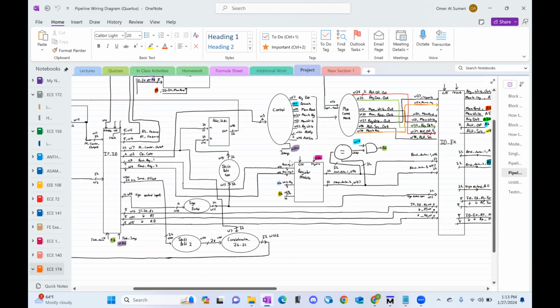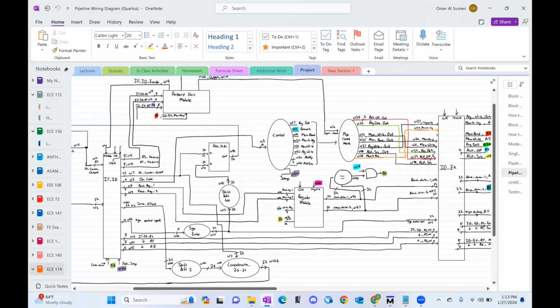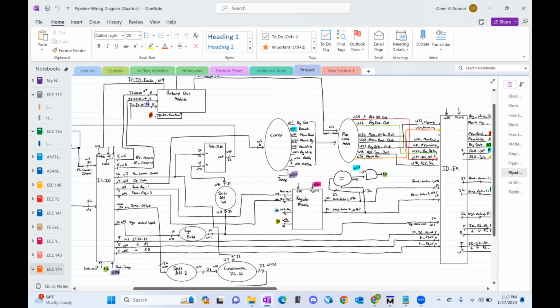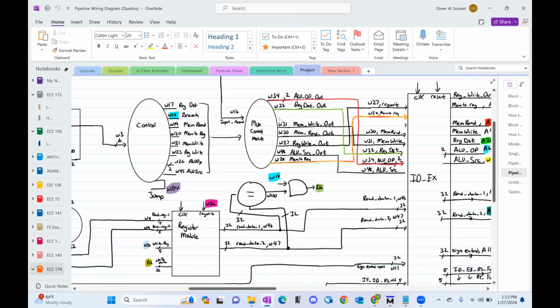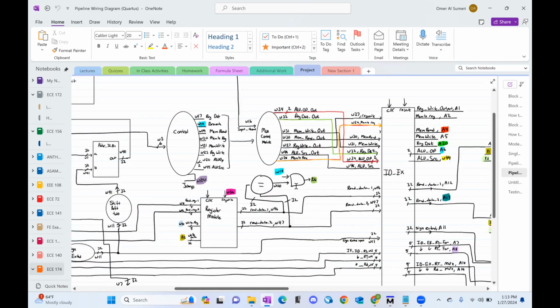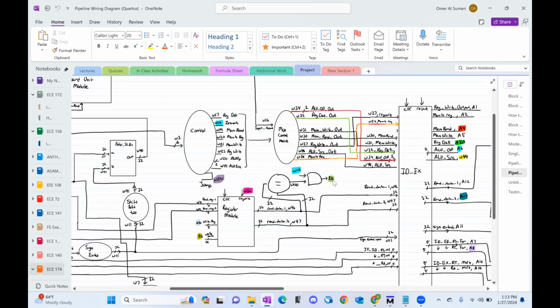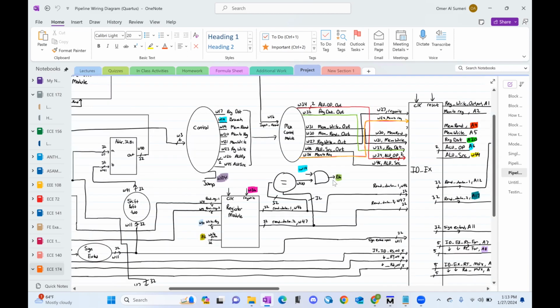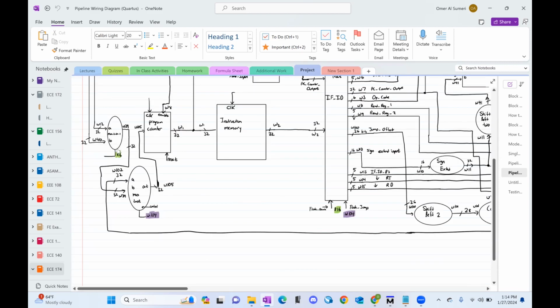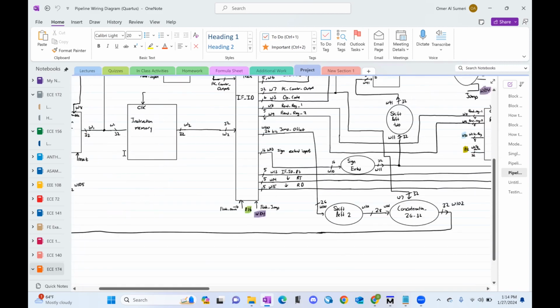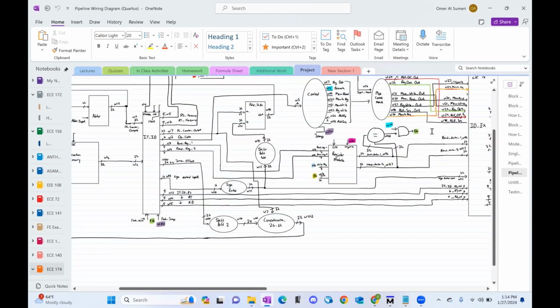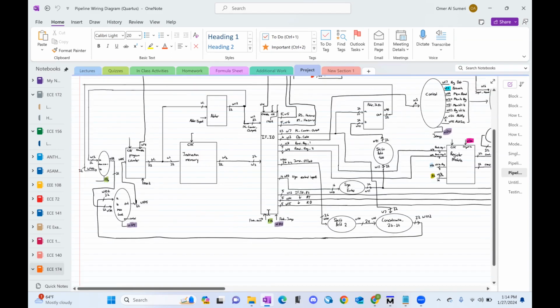And the modules here that are kind of important are the main control unit, the register module, and then as you see here, there's a mux of different size used here, a comparator and an AND gate, and then these highlights here are used to reference an output. So for example, this L16 output of the AND gate connects to the input of this mux. But it'll be unnecessary to draw a line, so we just use the same color highlighter to depict it.